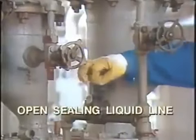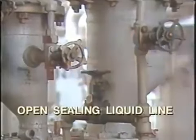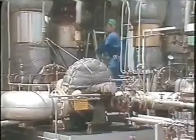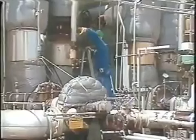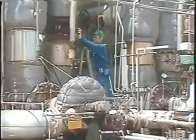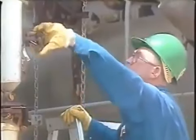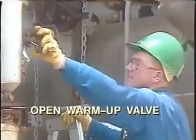Also, open the line which circulates sealing liquid to the stuffing box. Pumps which are used for pumping hot liquids must be warmed before the pump is started. This will prevent damage to the pump by unequal expansion of parts when the hot liquid enters the pump. If the pump is used for hot liquids and is not always kept at operating temperature, open the warm-up valve.